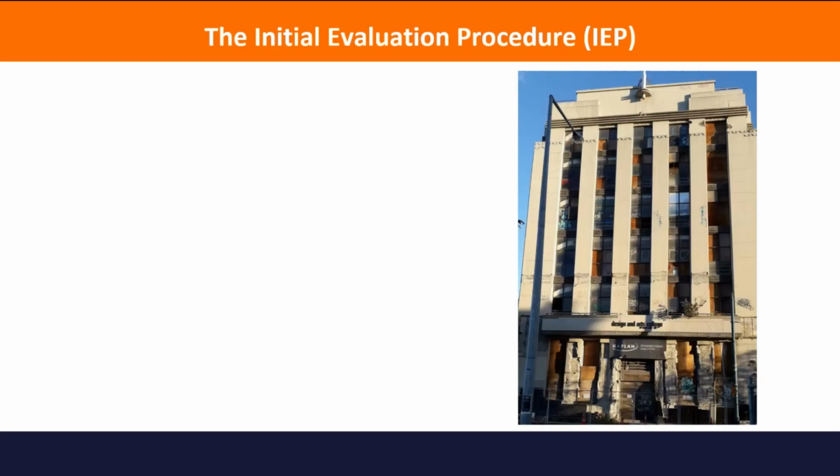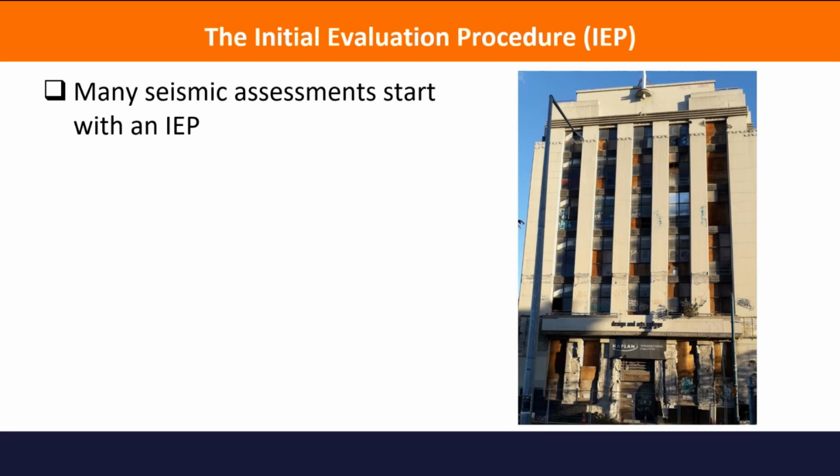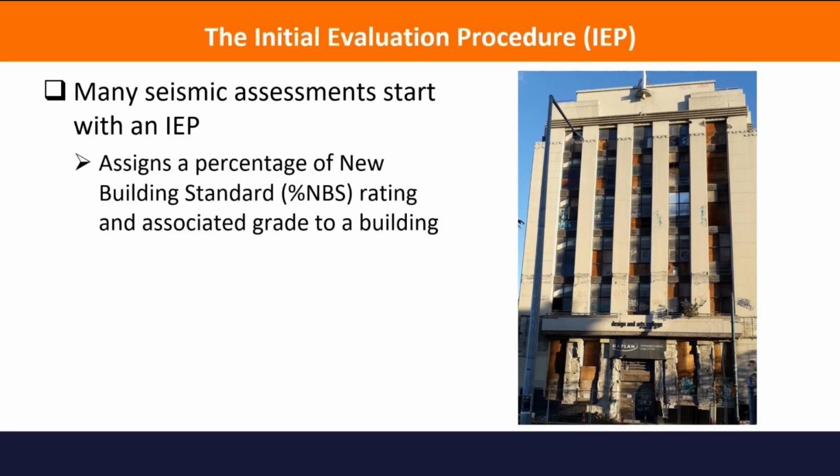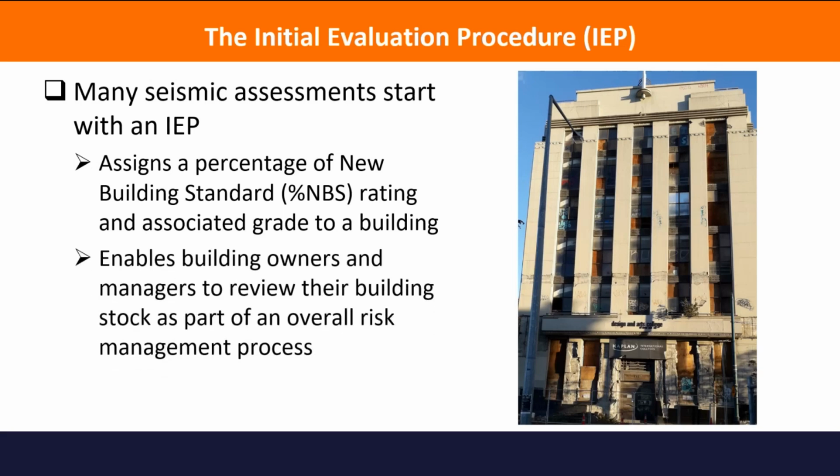So again, an example in Christchurch, what is the initial evaluation procedure? So it's the start of the process of doing a seismic assessment of an existing building. And what it does, it assigns a percentage NBS. NBS stands for New Build Standard. Keep up with these acronyms. And it gives you a rating and a grade associated with your building. And it enables your building owners and building managers to review their building stock.